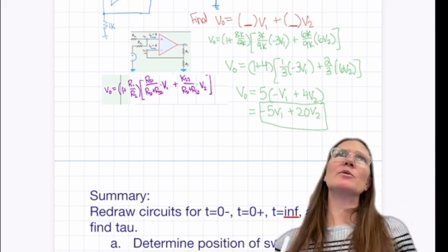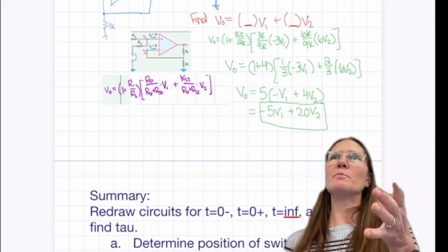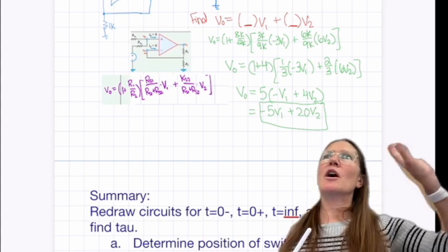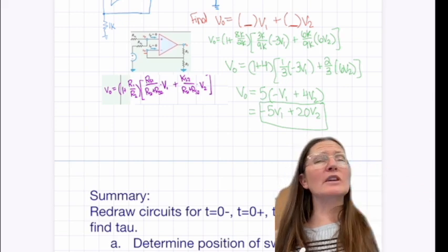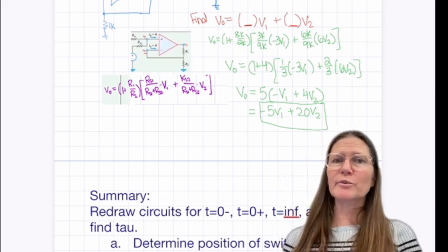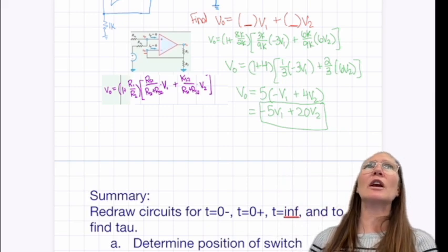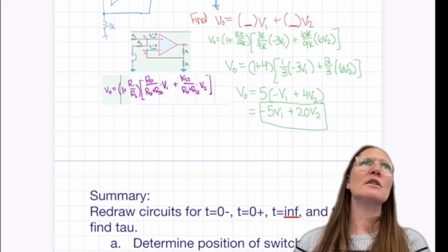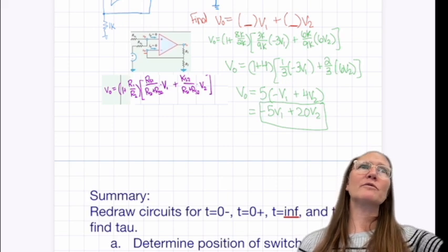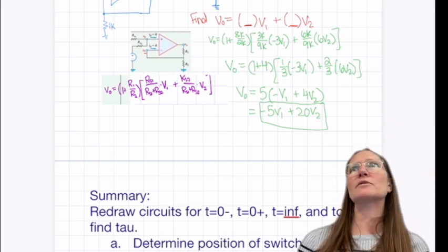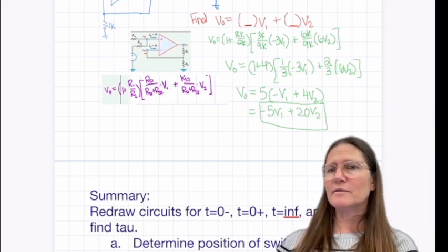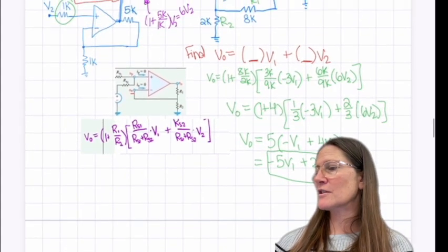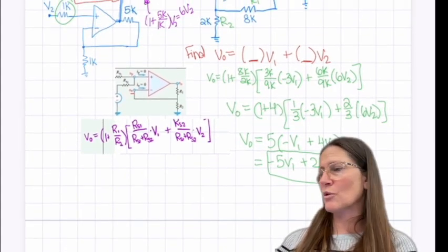So these are the kind of questions you're going to see: identifying the op-amp configurations, either being asked to identify or design, like what would this value be for this resistor to give you this particular gain, which is some of the questions you've seen, or it could be asking you for these cascaded op-amps. So with this one in particular, you do need to identify what resistors affect the answer and which ones don't.